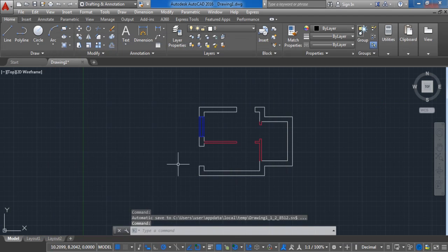By default, you start working in a limitless 3D drawing area called model space. That is here. You decide whether one unit represents 1 millimeter, 1 centimeter, 1 inch, 1 foot, or whatever unit is most convenient. You then draw at 1:1 scale. Here you can draw everything that you want, in 2D space or in 3D space.